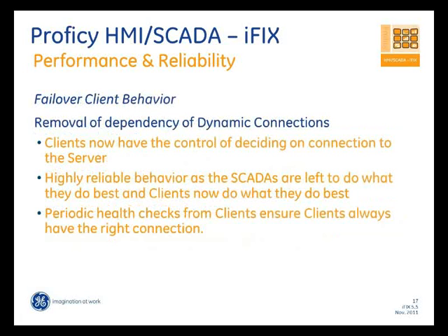The other is really the client behavior in the new iFix enhanced failover environment. We just had a lot of complaints around clients flip-flopping between SCADAs, or clients being stuck on a particular SCADA when you go to a maintenance mode, or when the servers fail over. What we did was we looked at the systemic problem that it was causing, and the first one was definitely the fact that we forced dynamic connections to be used, which was one of the key elements causing this problem. So we designed the client behavior to go away from the dynamic connections.